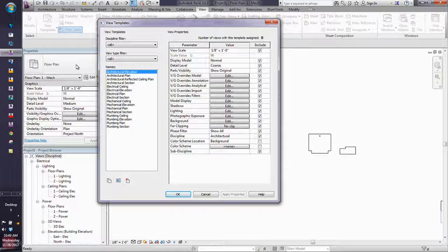So what we did, to make this guy happy, is I went ahead and got the model for the blower, put everything at the right place, and it was just a raw model, just a simple box is all it had in there. But when we got to the plan views, I took the cut drawings that we actually got from the manufacturer, took the 2D drawing in, dropped it in as a plan view, as a plan symbol, and then that's what he saw in the plan. So he got his picture he was looking for, but we didn't have to go into the detail level of the model. So yeah, that's a great thing to do.